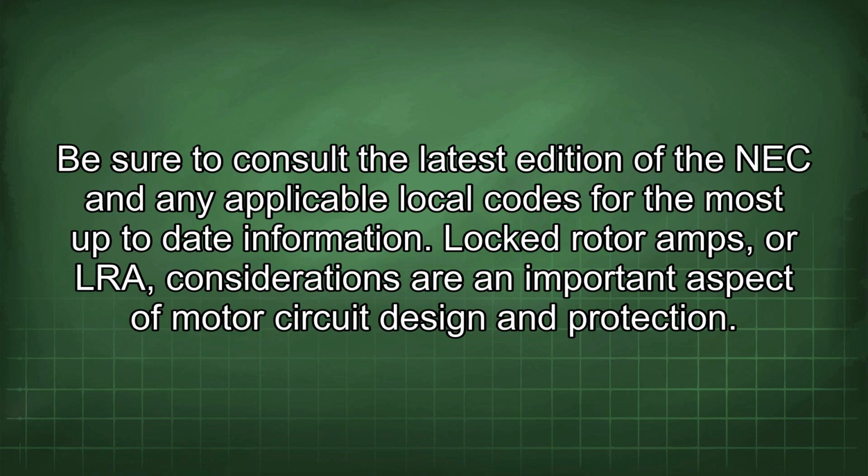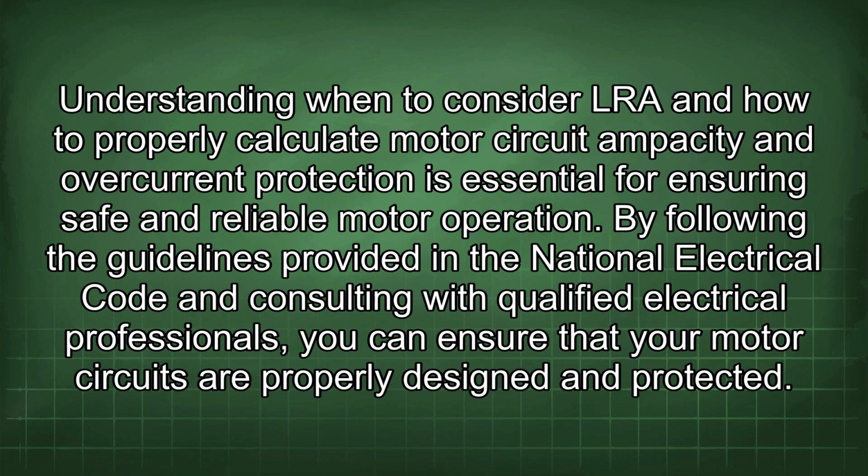Locked rotor amps, or LRA considerations, are an important aspect of motor circuit design and protection. Understanding when to consider LRA and how to properly calculate motor circuit ampacity and overcurrent protection is essential for ensuring safe and reliable motor operation. By following the guidelines provided in the National Electrical Code and consulting with qualified electrical professionals, you can ensure that your motor circuits are properly designed and protected.